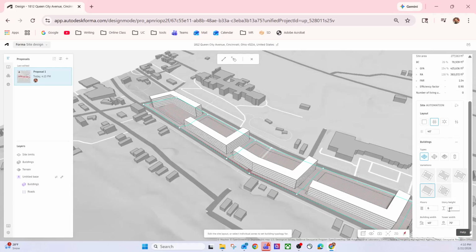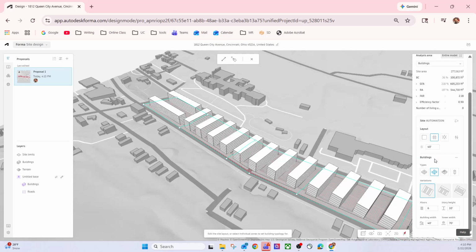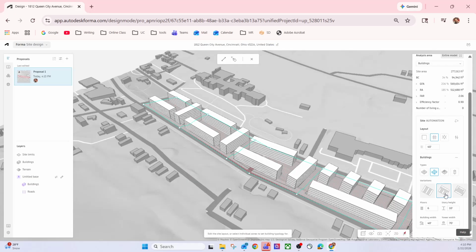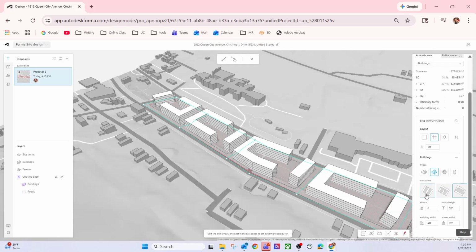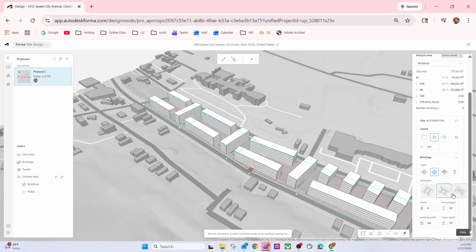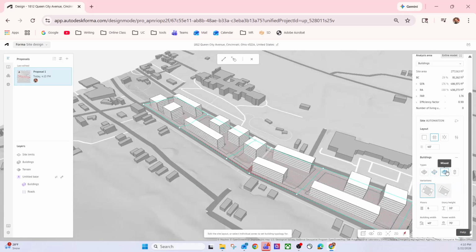You can also change the height. By default it's 10 feet, right? So this is the kind of parameters you can actually do in Grasshopper as well. So this is a basic type called city blocks. You can also do a linear kind of solution. This is in a lot of large scale real estate development. It's basically a cookie cutter kind of approach. So you can have these different settings. Again, you can manipulate this. You can also do mixed, which has both block and linear mixed together.